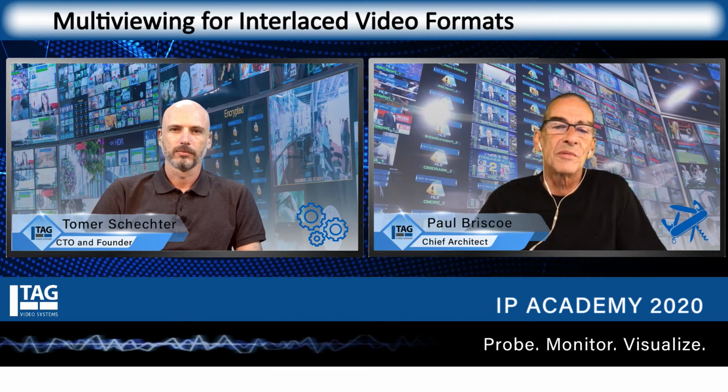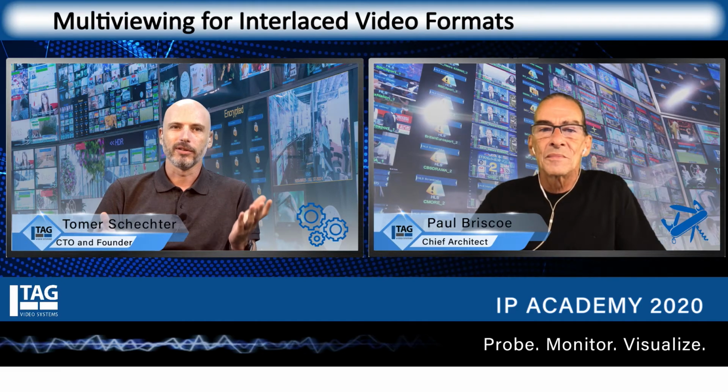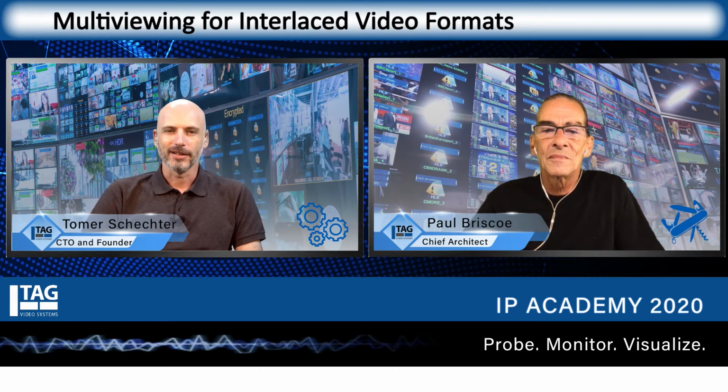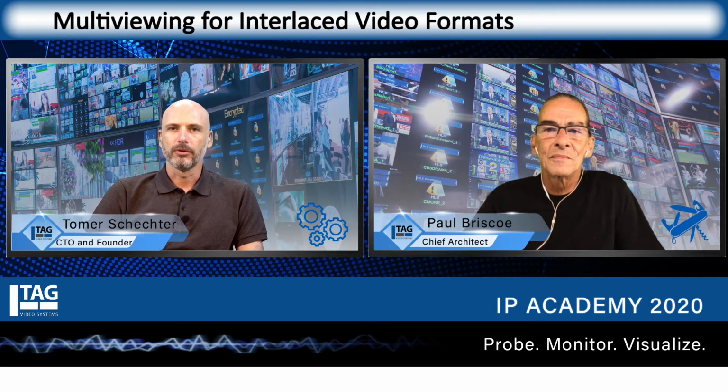So then basically in compressed systems, we really want to stay away from interlace as much as possible and simply always use progressive imagery. Is that right? Yeah, the quality that you'll get, and again, when you're talking about compression, quality is a parameter of quality and bandwidth. It's one instead of the other. So for the same bandwidth, the quality that you'll get will be better for progressive content than interlaced content.